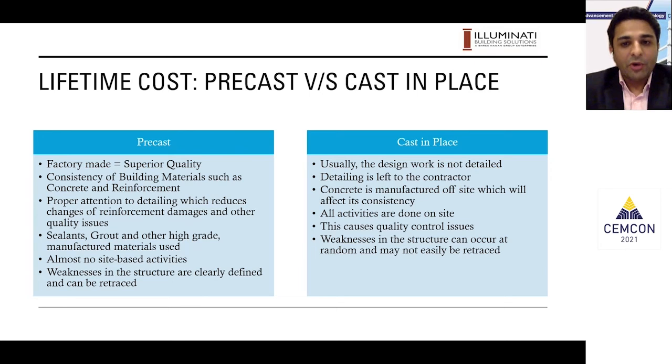When we focus on things like the detailing and the smaller things with respect to the design, with respect to the production and the installation, we get a superior product that has less chances of failure. With respect to the use of grouts, sealants, and other mechanical joints on site, the serviceable life of the structure increases. The most important thing is because of the high level of planning in precast, it is easy for us to foresee where we might go wrong, where there might be a problem and where there might be a failure in the future, and we can try and reinforce that at an early stage.